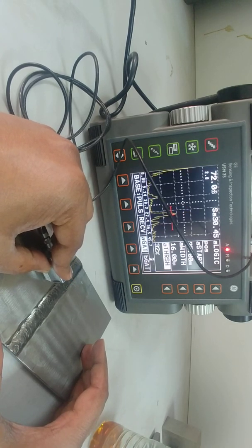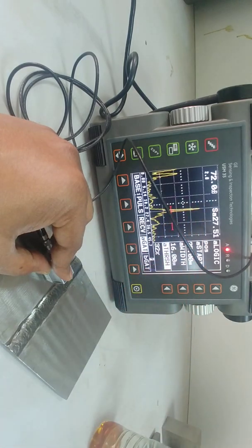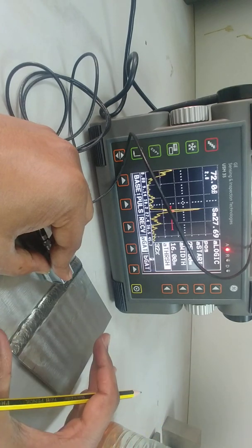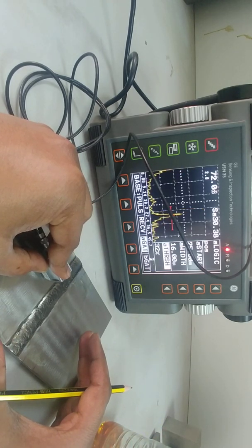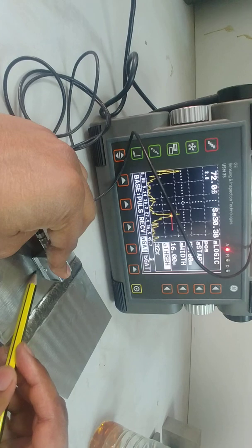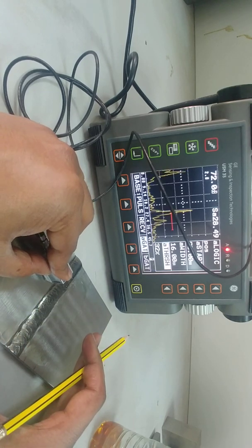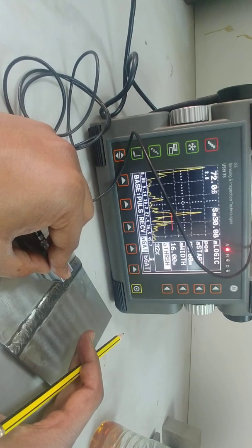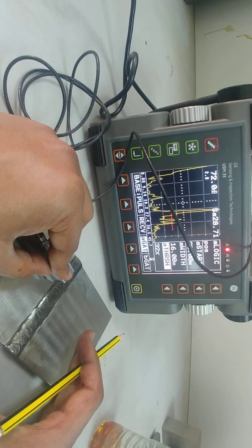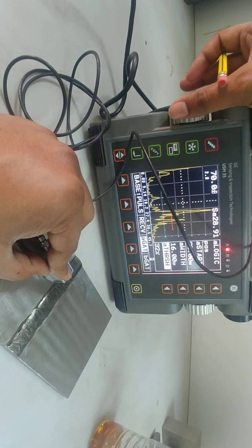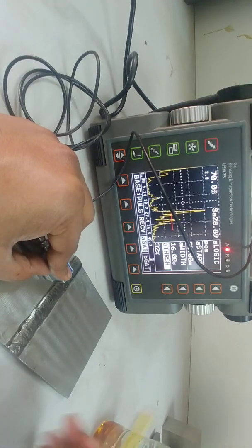So how you're calculating is, you're trying to look for this peak. I'm just going for this peak. This is something like at 80%. Now, if I just move it, it becomes smaller. So if I want to measure the size of this one, I have to measure this size from this point, move it till it reaches the maximum somewhere here. Sorry, I think I lost it. Yeah, somewhere here. So this is 40. Then if I move it, it's becoming 80. Oh, it's becoming too much high. So try to get the peak. After getting the peak, make it to something like 80 or 90%.